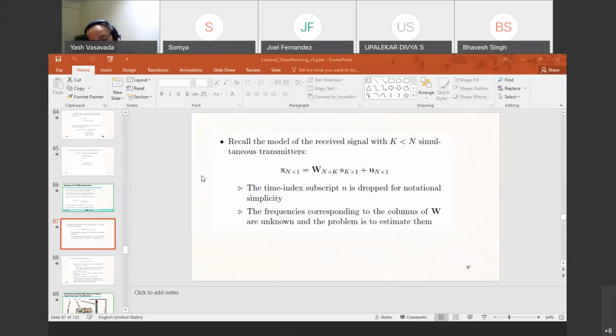The other thing that I wanted to mention about the MUSIC algorithm is that it actually does away with the need for a bank of bandpass filters. You don't need them, because in that equation of the MUSIC algorithm that we saw last time, we have a summation of dot product magnitudes squared in the denominator.